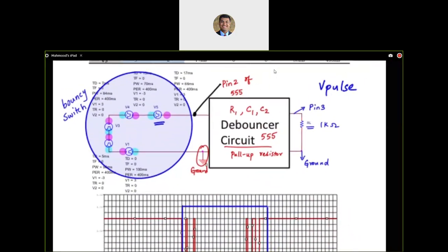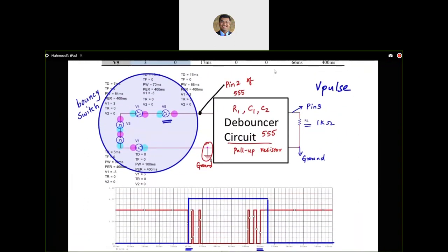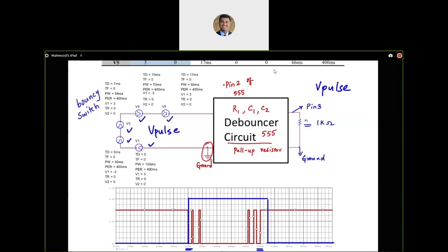So if I zoom in on, this is page 2 of project 3 writer, and let me erase this so that you get clarity. So there are 5 voltage pulses that you use. In capture, you would have to use the part V pulse. So there are 5 of them, and there is a polarity to this. So of course, to any voltage source there is a positive and negative terminal.